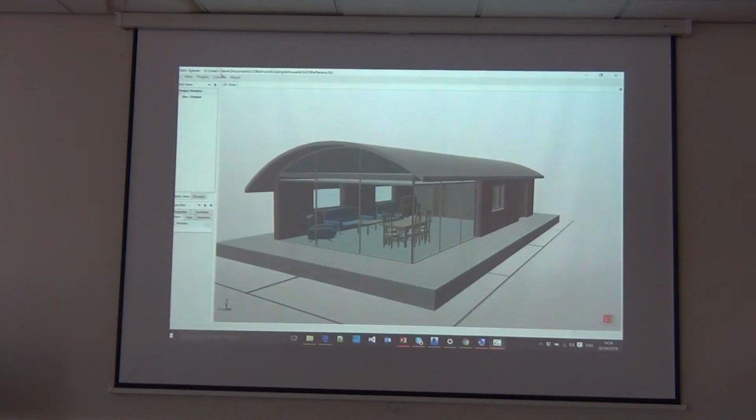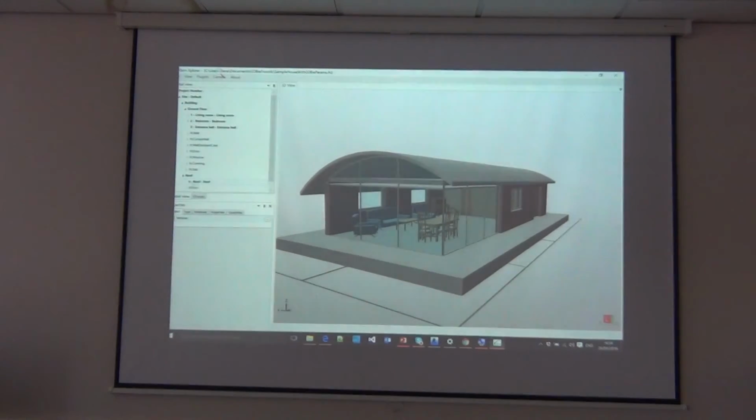But somebody asked me what's the structure of BIM. So we configured this to show you the structure of an IFC model. What you can see on the left-hand side is we have a project. Within the project there's a site. Within the site there's a building. The building has a ground floor and a roof. And within the ground floor there's a living room, a bedroom, and an entrance hall. So you've got a number of consistent ways of viewing. This is called the spatial hierarchy view, and it lets you see it by spaces.